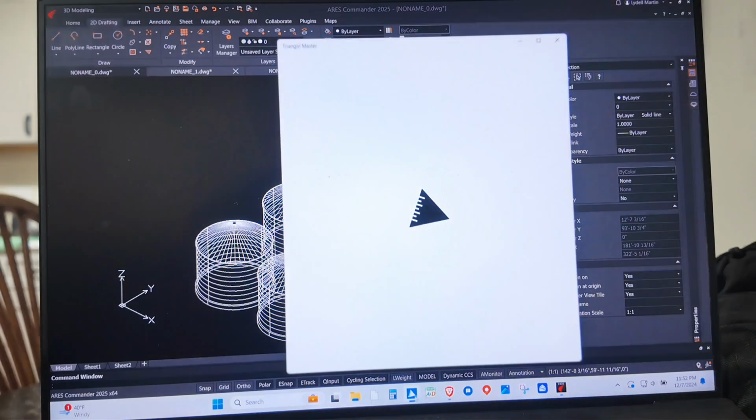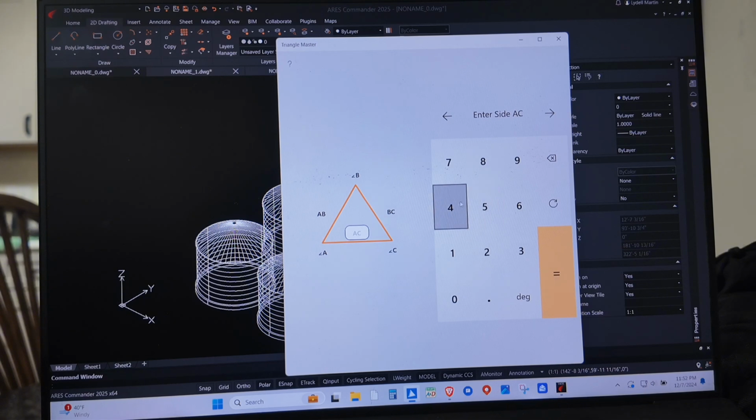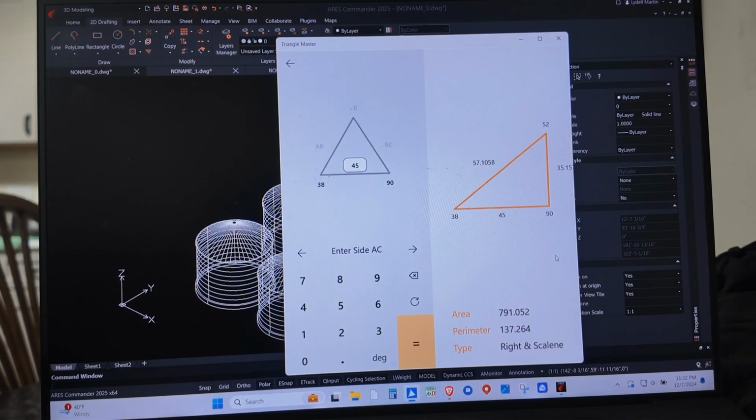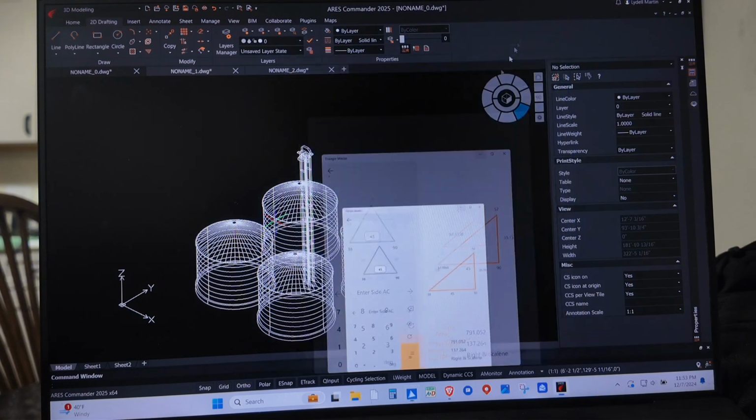So if we go to our triangle calculator and we say 45 foot away, minimum of 38 degree slope, we have to be 35 foot taller. So 51 foot plus 35 is 86. Plus we have our distributor, which is almost 5 foot. So that's 86. That's 91. And then we have a cushion box. So we need 95 foot elevator at least.